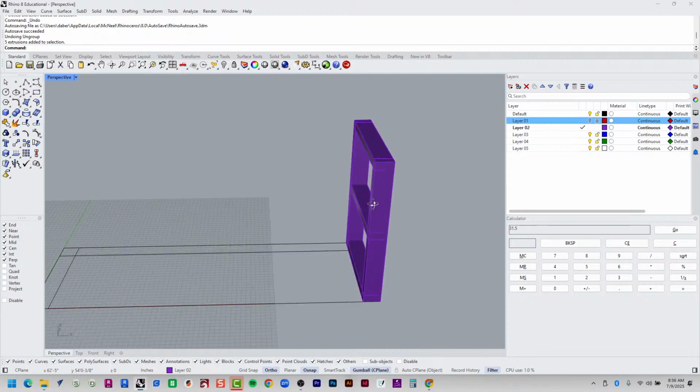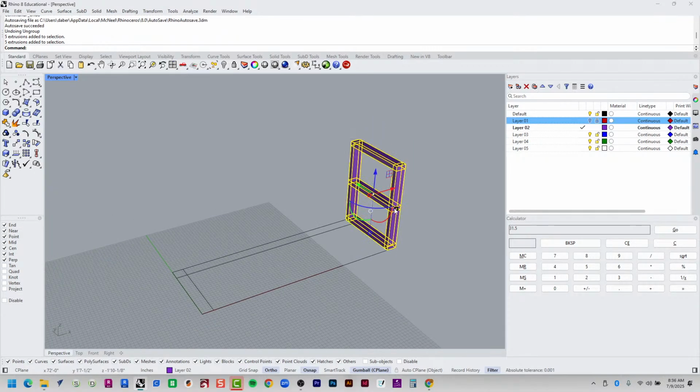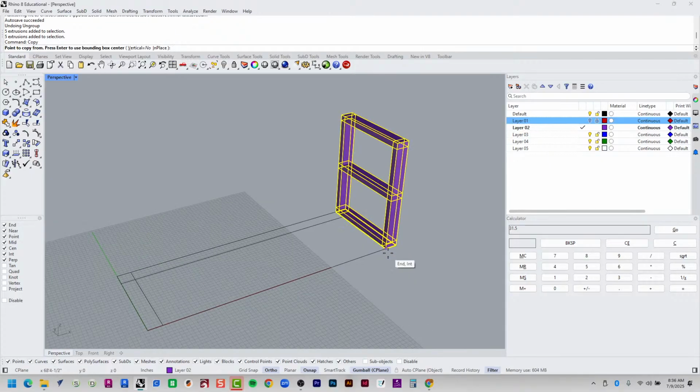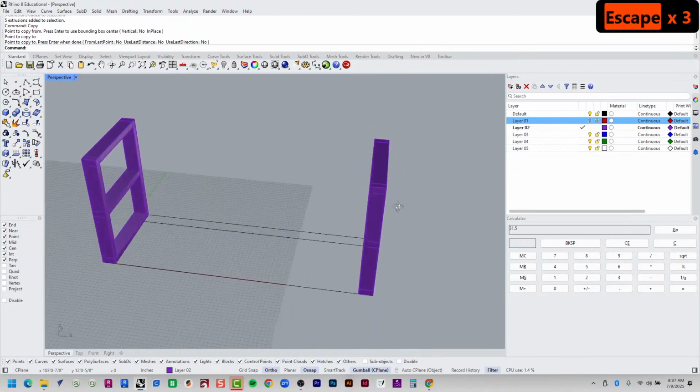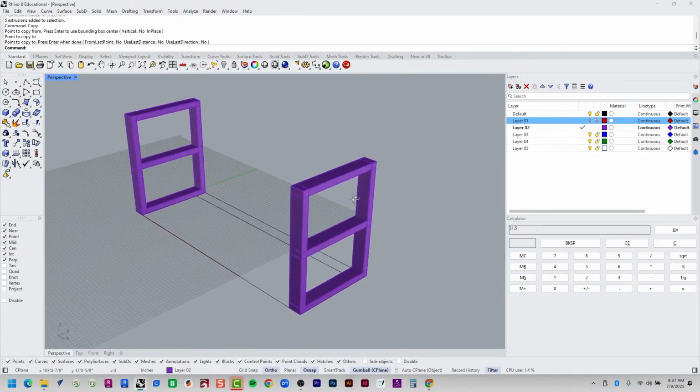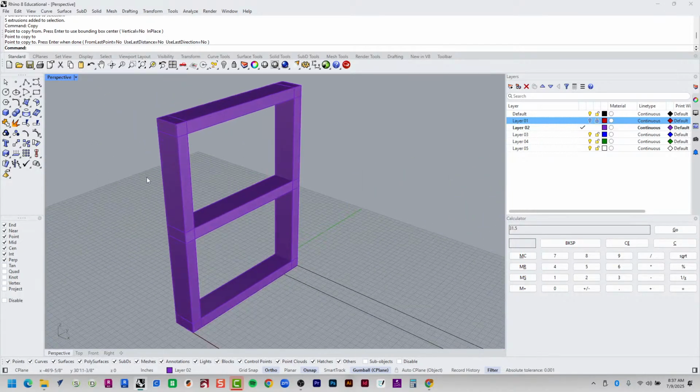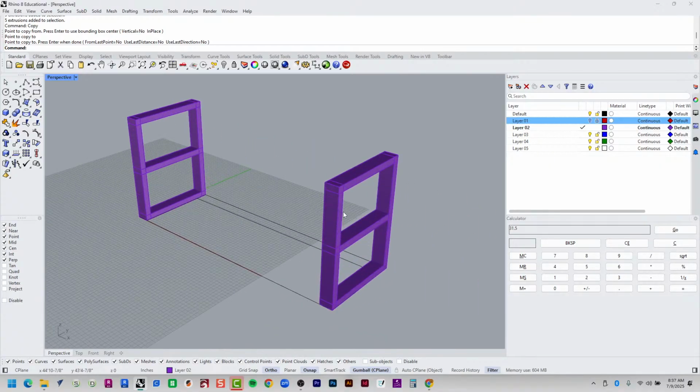So now that I did all of that work to create this wall in Rhino that represents the frame CAD, I'm going to type in copy, and I'm going to copy it from this endpoint and move it to this endpoint, and boom, there's two, right? I could have done all that same work all over again, spend 10 minutes making that wall all over again, but if I just do it properly once and copy it over, I just saved 10 minutes.